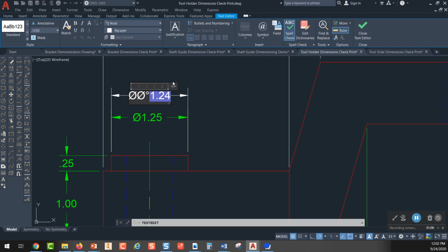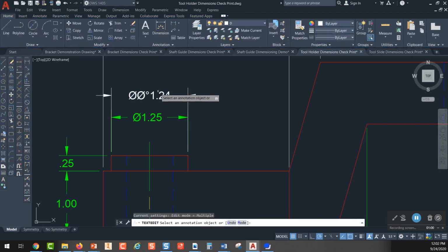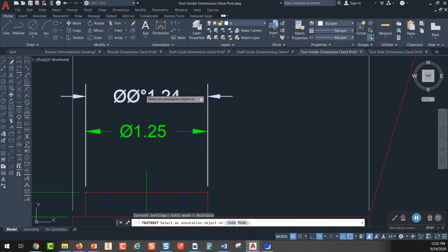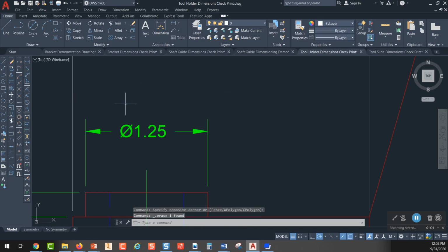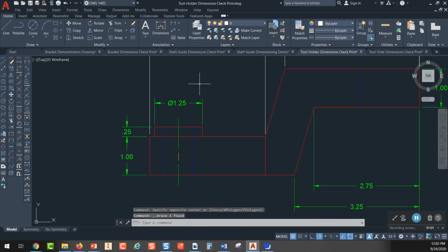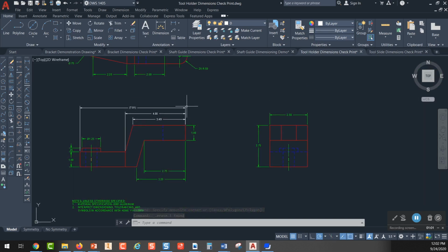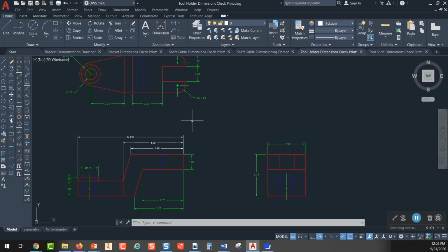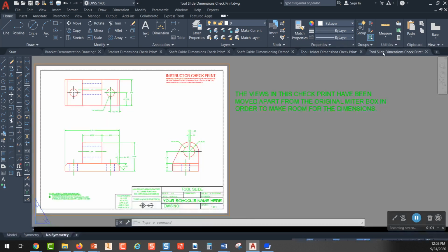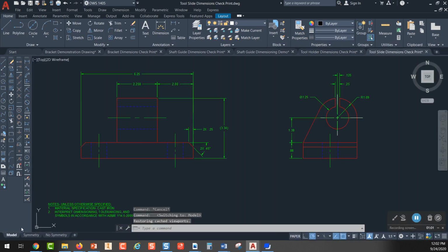Like I said, this is back in the dark ages. But the point is, that stuff's still in there. There's a lot of that old DNA still in AutoCAD. And so some people still like to type %C when they need a diameter, or %D when they need a degree symbol. So I think it's cool to know that stuff, though you don't have to, because you've got the symbol option. All right, so that is the third drawing, and then the fourth drawing is this guy right here.